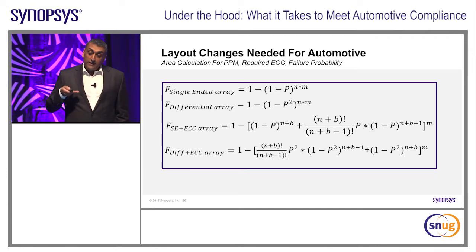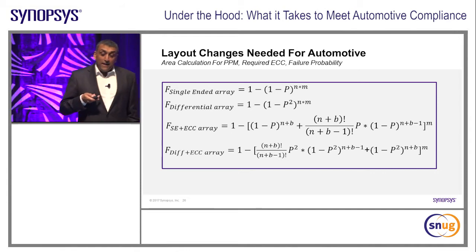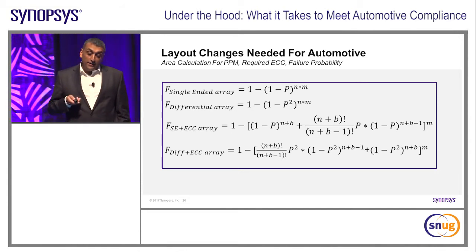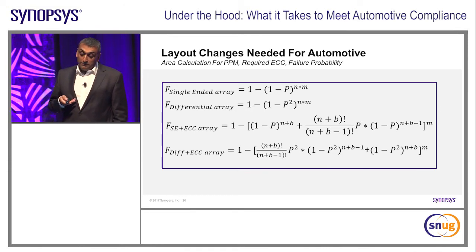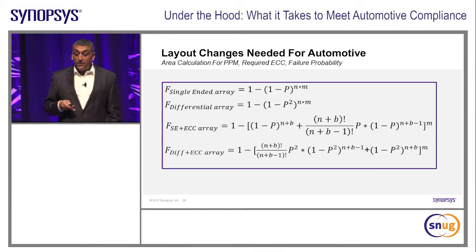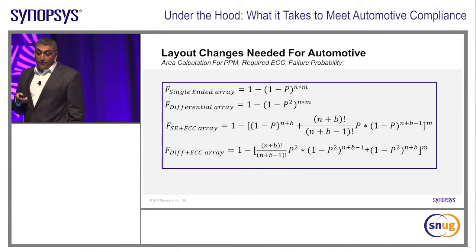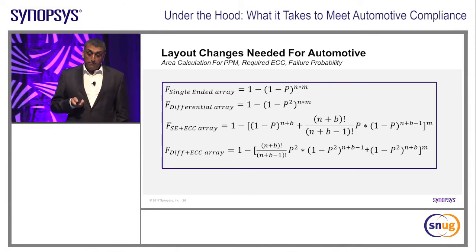So we took an NVM technology, and we looked at the impact of that NVM array in terms of failure probability at elevated temperatures, right? The terminology here is real. This is how we actually size devices for some of these things. F represents the end-of-life failure rate, expressed in ppm.